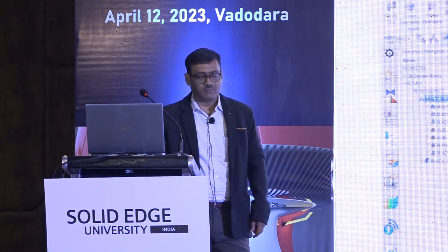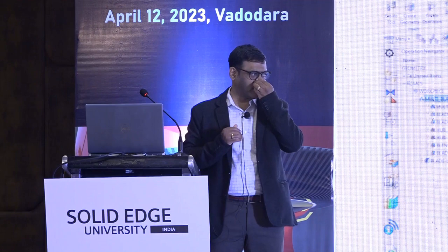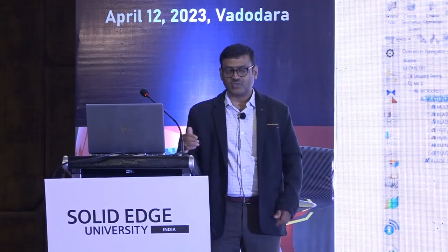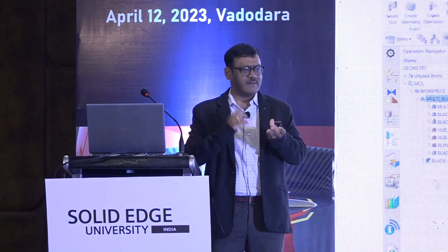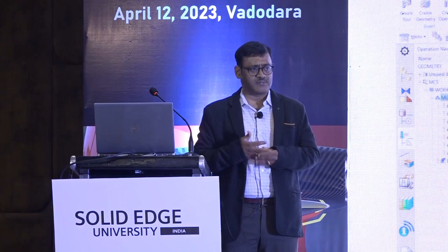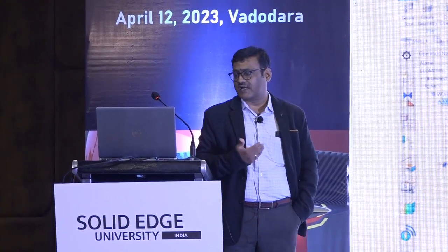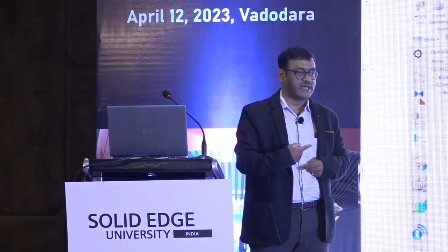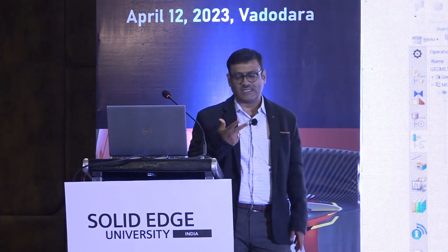Then there are some more things which most customers do today: complex parts. I'm not sure how many of you do complex programming here. Let's say impeller or blisk or rotating equipment parts. I know Siemens has been using this for a long time. We have something called multi-axis blade. This is also part of Solid Edge CAM Pro, the latest version of NX and Solid Edge CAM Pro, where you create your toolpath the first time and then rotate that by 80 degrees or 45 degrees, depending on the axis.